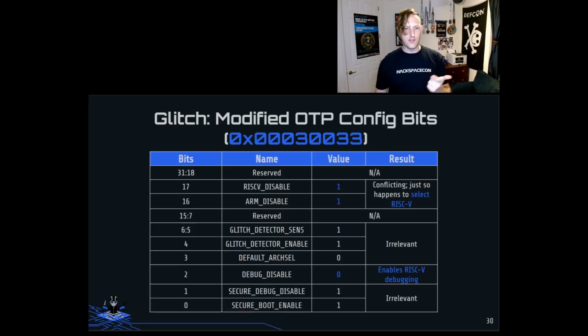This is also very interesting because for this challenge, the secure configuration meant that the RISC-V cores were permanently disabled. And instead, because of the way this glitch happens, we're actually able to re-enable those cores. And now we have the RISC-V cores, which provide full memory bus access, and we can attach a JTAG debugger to that to read the secret out of OTP memory.